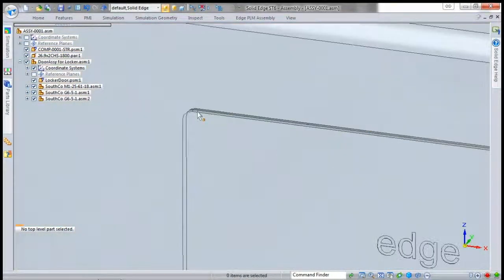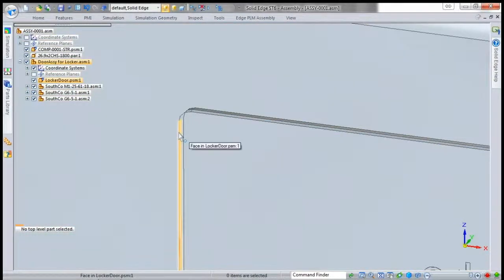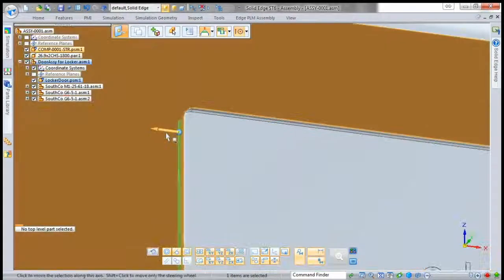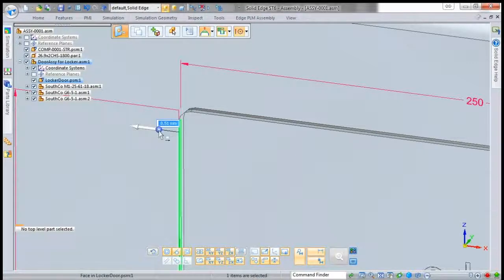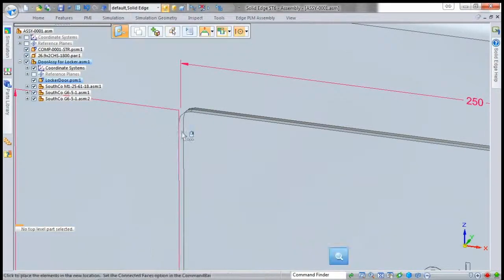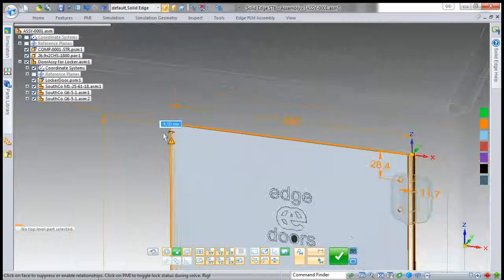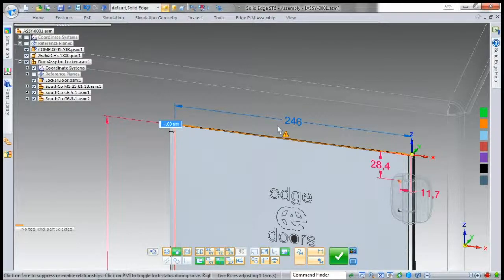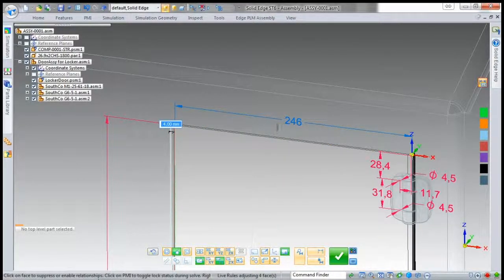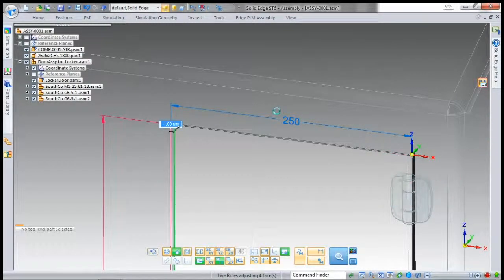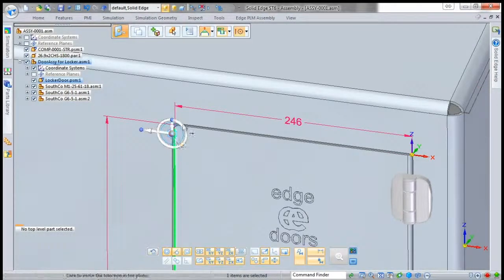You'll notice that this door doesn't quite fit, so what we want to do is we want to modify this door width to give 2mm clearance. And then we'll just drag it back to the vertex there. Now don't worry that it hasn't changed it, because we just need to relax this dimension and then it makes that change, and we've got our 2mm clearance there.